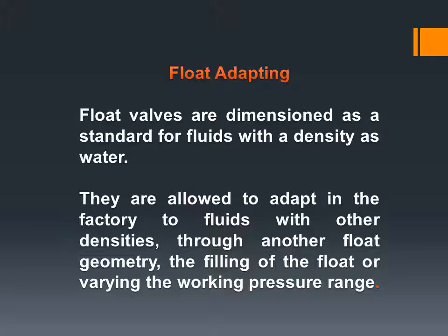Float adapting. The float valves are dimensioned as standard for fluids with a density like water. They can be adapted in the factory to fluids with other densities, through another float geometry, the filling of the float, or by varying the working pressure range.